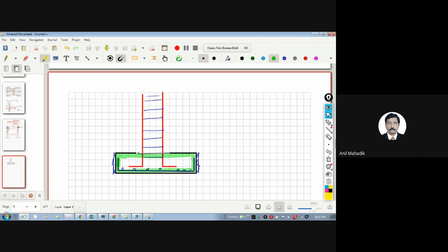So today, let's say I have done the concreting over here. Fine. Now I need to do the concreting of the column tomorrow, but generally people don't do it the next day. They will do the starter. They will align this reinforcement because the column height is generally 3 meters or more, so this cage is not in place. So what they do is put concreting only within this zone. This portion only.